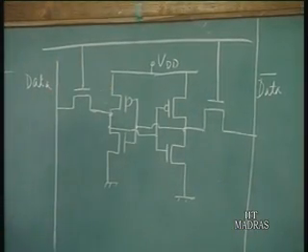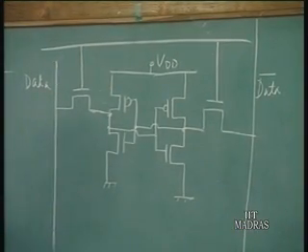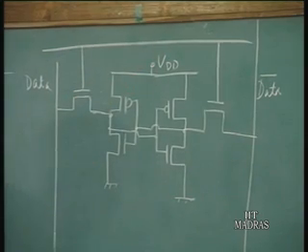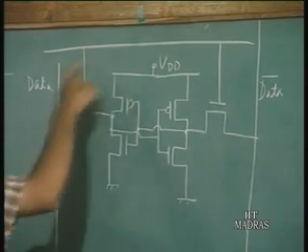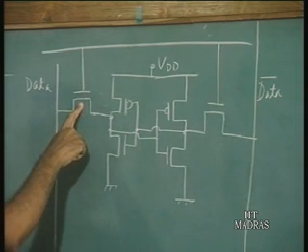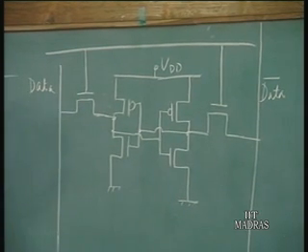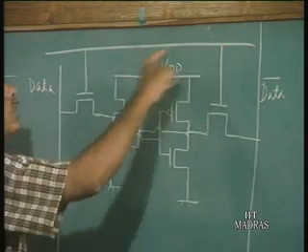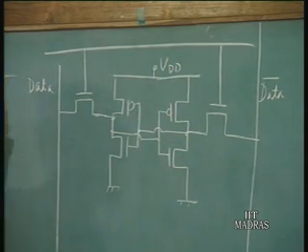Okay. Now, you have the word lines running all through the memory array. Now this word line is connected to the gate of these pass transistors, and we know that in a MOS technology the gates are usually made of polysilicon. So these word lines are usually run on polysilicon.